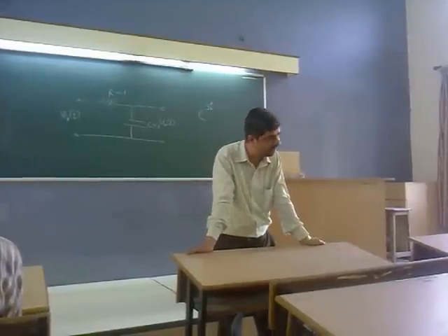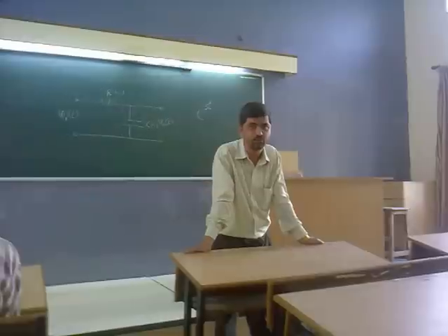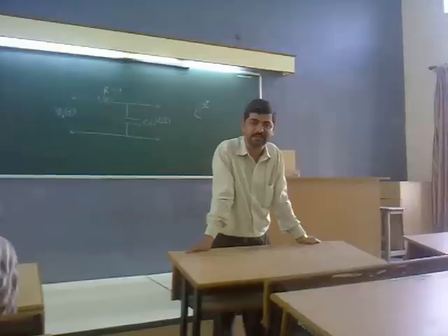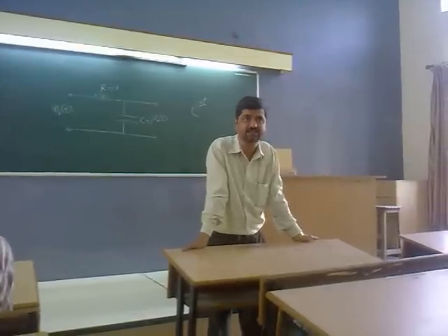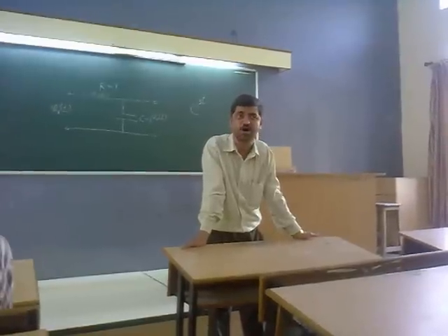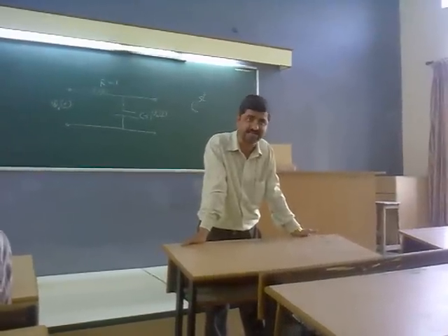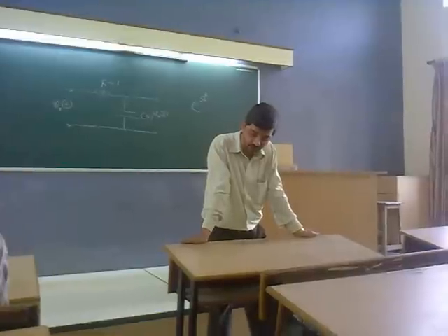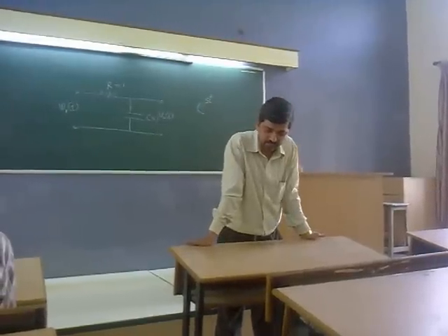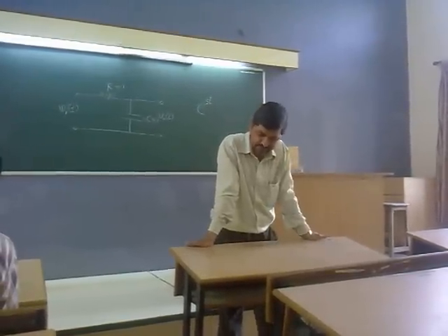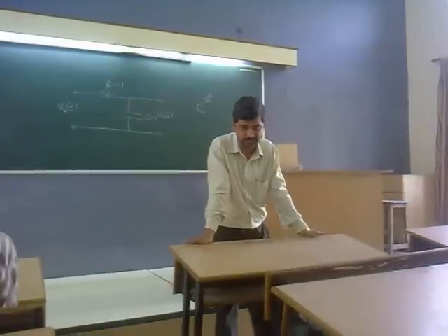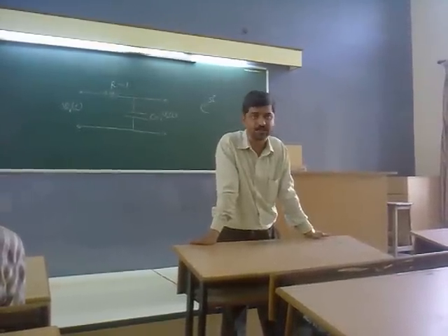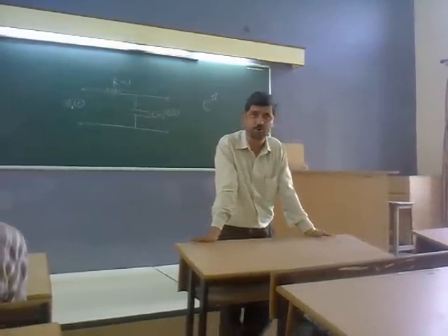Once we are well aware of the plotting of e raised to st, we are aware also of the manipulations with e raised to st. We can displace it in the same direction from the origin, or we can displace it to any arbitrary position, or we can rotate it on a circle. If we rotate it on a circle, its amplitude remains fixed. If we displace it in the same direction, then its direction remains fixed. Or if we rotate it in an arbitrary way, both change.